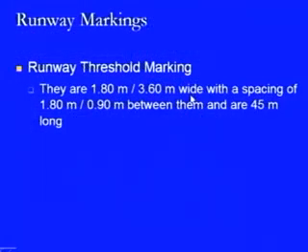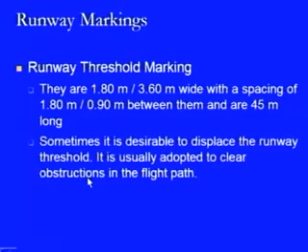These are generally 1.8 meters or 3.6 meters wide with a spacing of 1.8 meters or 0.90 meters between them, and are 45 meters in length. So, these are the specifications for providing these markings.